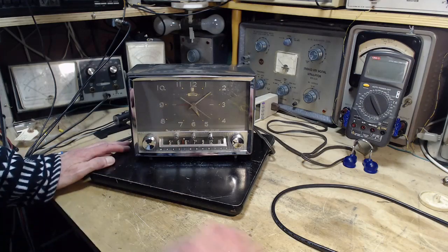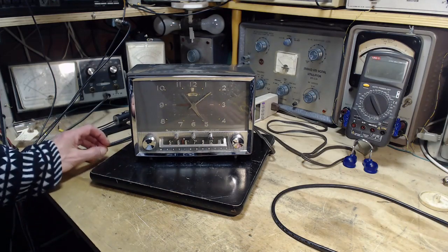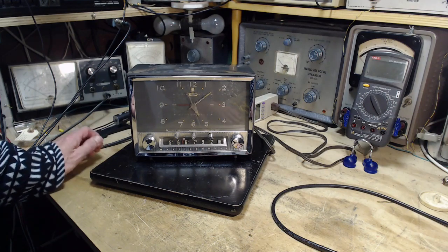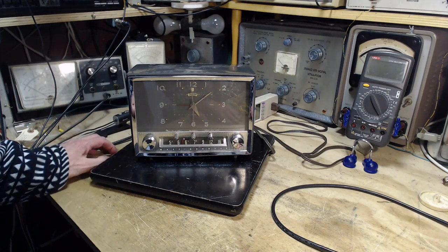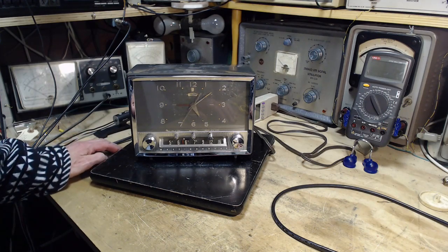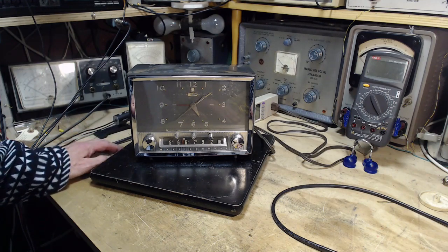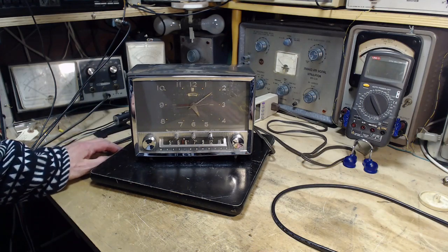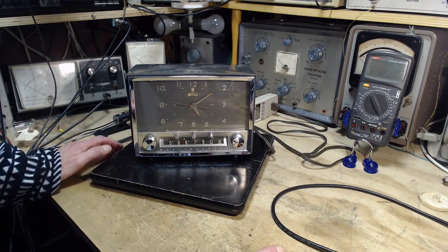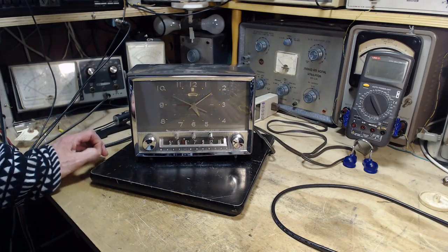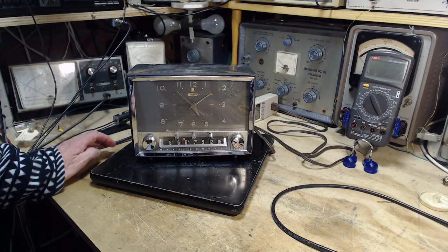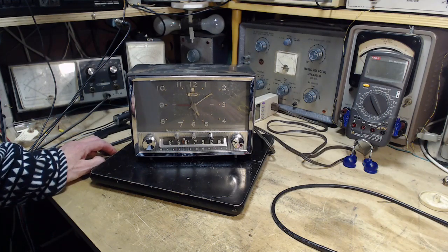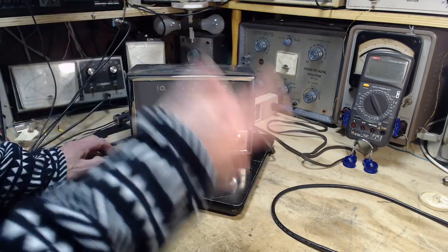and I think what that says to me, based pretty much on recent discoveries with some radios that I recently worked on, is the IF is oscillating in this radio, probably from some kind of accidental feedback from the output of the IF circuits back to the input, or something like a capacitor is failing to drain away or eliminate an RF signal where it should eliminate it, and that signal is getting on further into the radio gain, probably supporting this feedback deal.